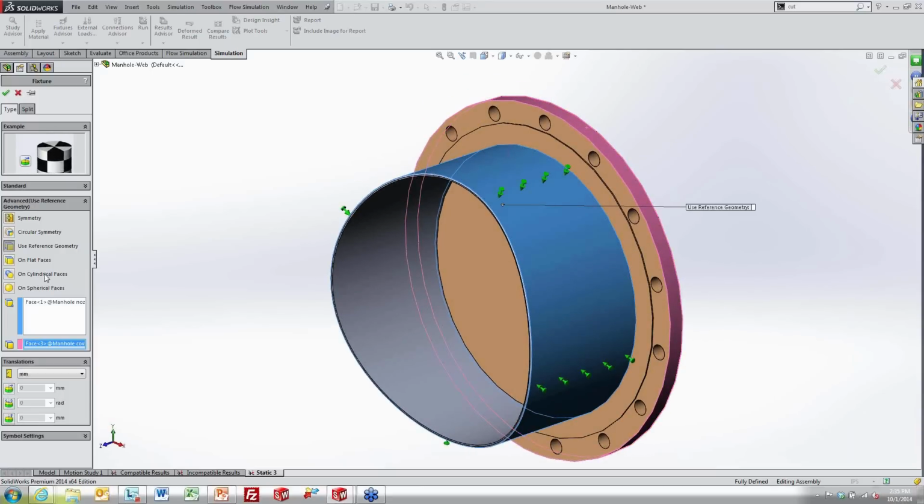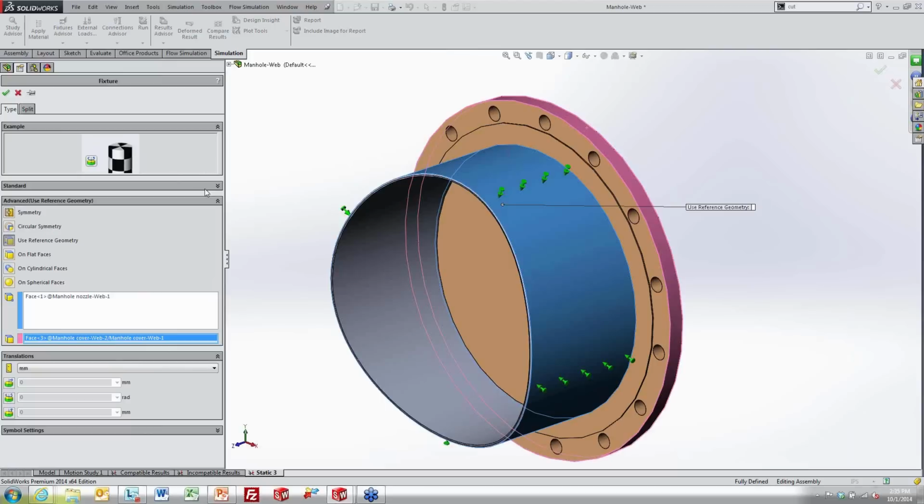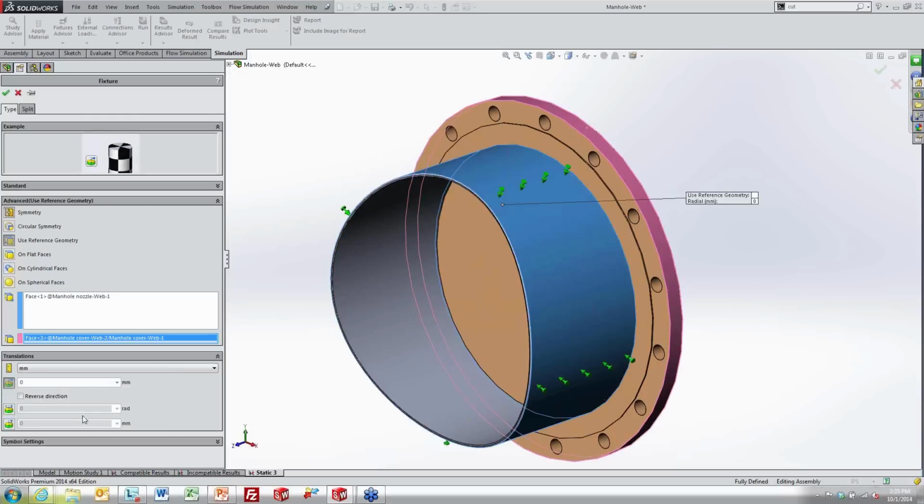Now to describe what those all mean, the pictures can be very, very helpful to you. Look at this very first one. This is expanding the radius in and out. This one's allowing the face to rotate about an axis, and this one expands the cylinder. If I checked one of these options and had this set to 0, this would forcibly prevent this face from being able to move away from the axis, being able to expand.